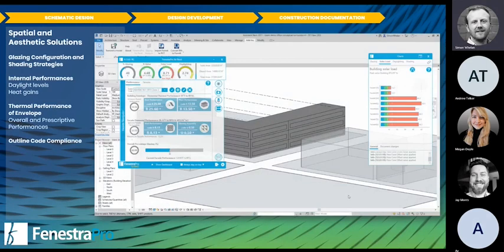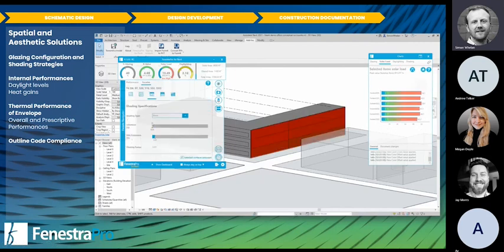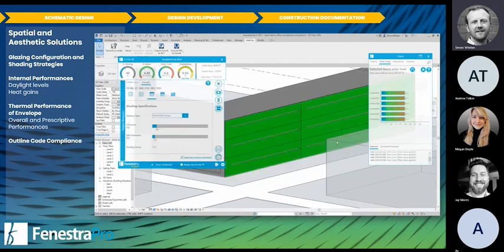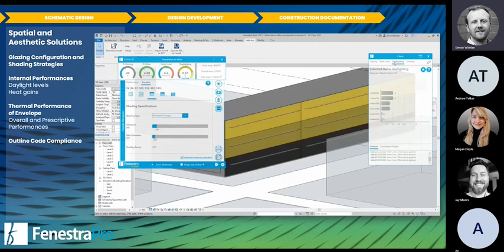So same kind of thing. It's still, we might be massing, we might be very early conceptually, or we might be into more detailed Revit models, but we're again maybe starting to look at glazing configuration, where my glazing is. If I've got 40% window to wall ratio under ASHRAE 90.1, where is that glazing situated? Is it loads to the south? Is it somewhere in between east and west, very little to the north? And then what are the impacts of those design decisions?